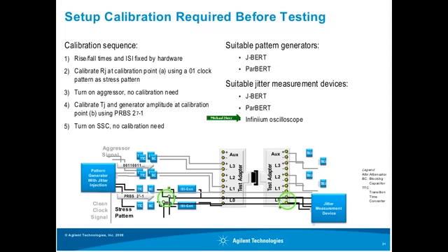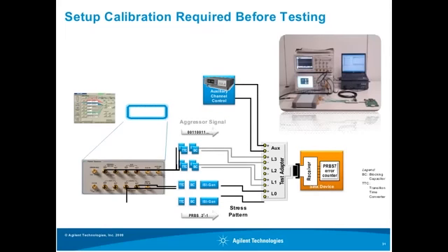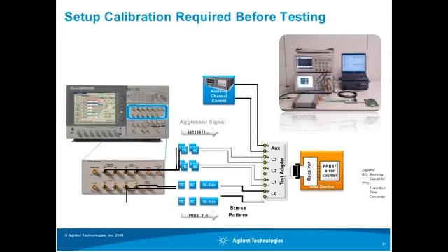So this is on calibration, and the setup looks slightly different for testing the receiver later on. I have a setup here with the Agilent JBERT B, but the JBERT A can also be used. As you can see here, we removed the second test adapter used for calibration and plug in our sink device. In addition, we now have the auxiliary channel controller connected to the aux channel.